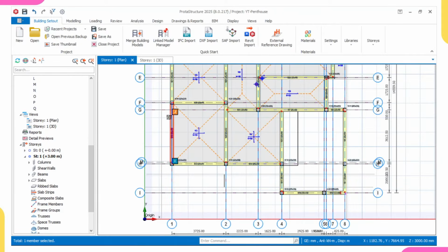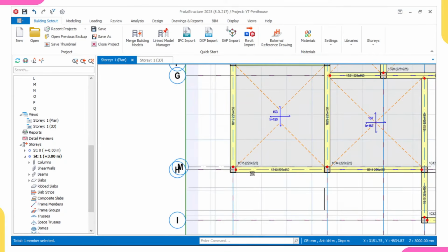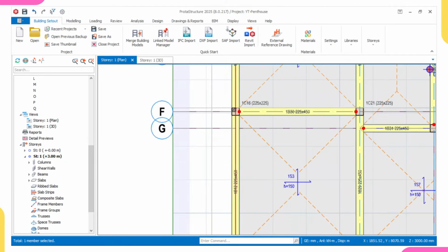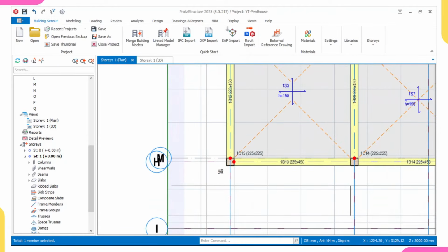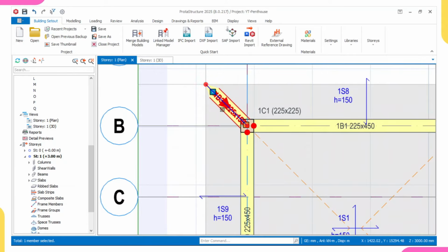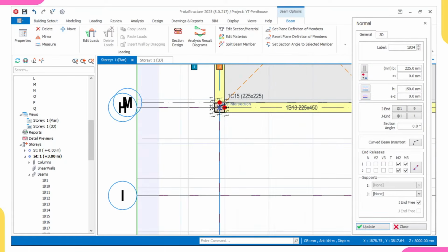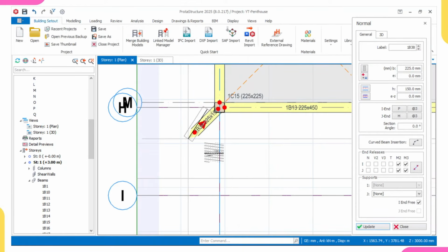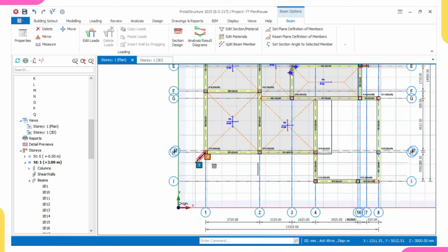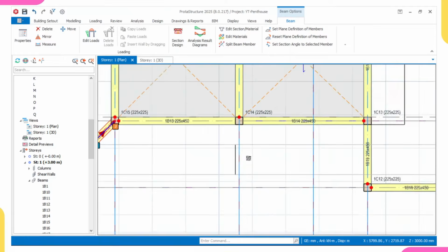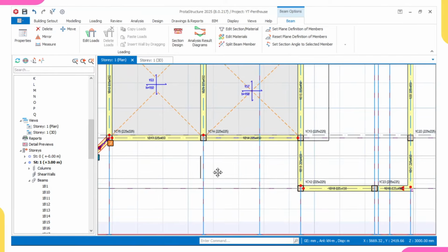So to continue my modeling, the next phase of this modeling now is we have to model here. We're having a slab from this point to this point. Let's remember we're having a column at this extreme, so we should have a hidden beam at that point. From here to here, we should have a hidden beam. So we have a slab here, then another slab at this point. These are the things that we're having.